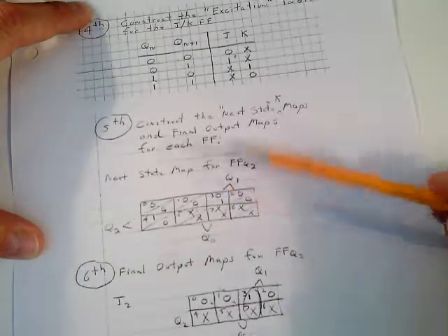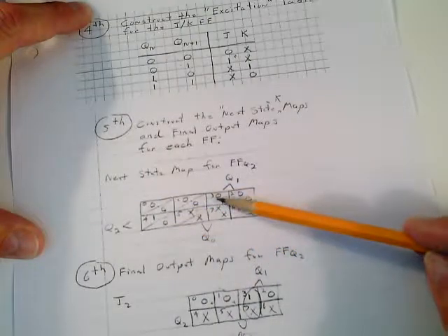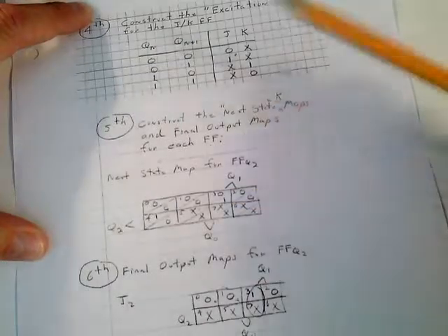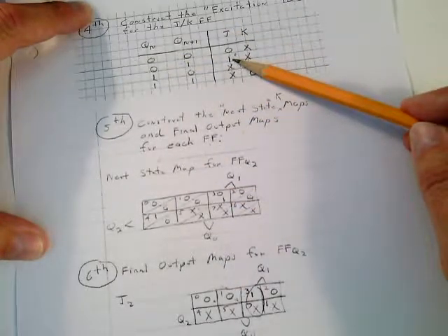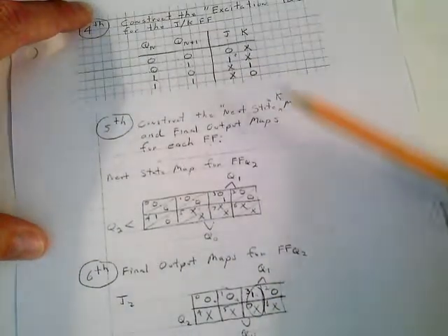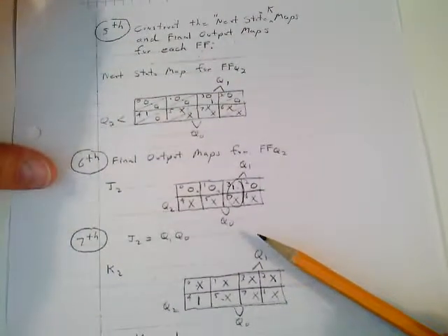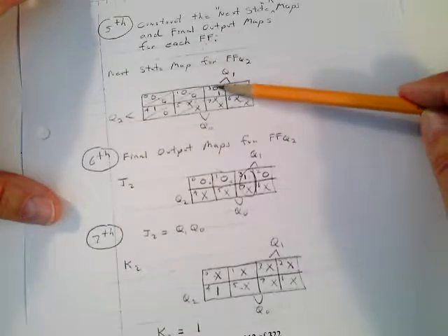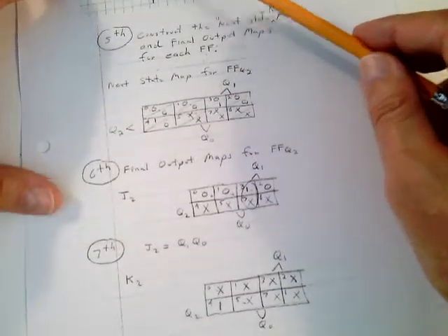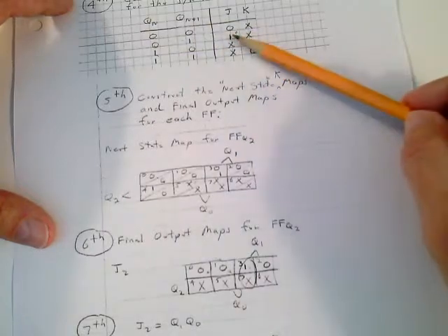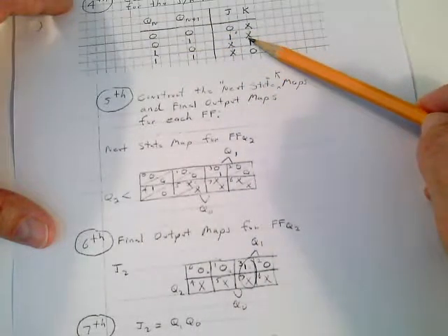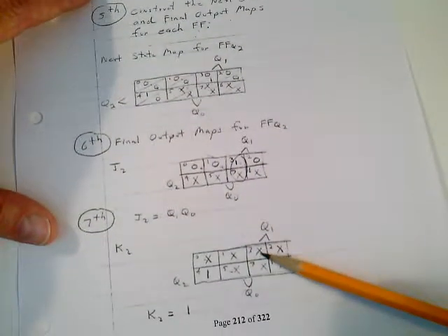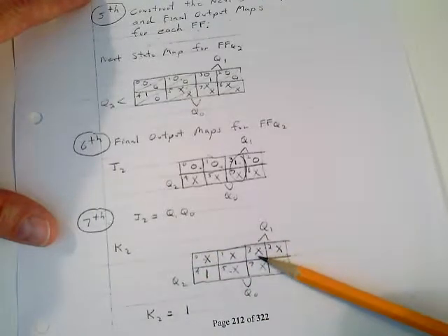Then you go to 3. You don't have to jump back; you can go right across here. Just remember you're going to subcube 3. You're in 0 and you go to 1. If you're in 0 and you go to 1, J is a 1 and K is an I don't care. Let's look at that one more time. For 3, you're at 0, going to 1. There's your J is a 1, and your K map is an I don't care.